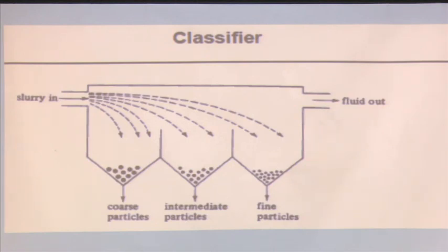And then suppose if I want to collect it in a continuous mode, what do we normally do? We put a valve here, and that valve is controlled by some kind of instrumentation that senses the load on it, like a pressure gauge type of system and a solenoid valve. It says that if accumulation is this much, I will be having this much pressure, then that solenoid valve automatically opens and drains out my particles.